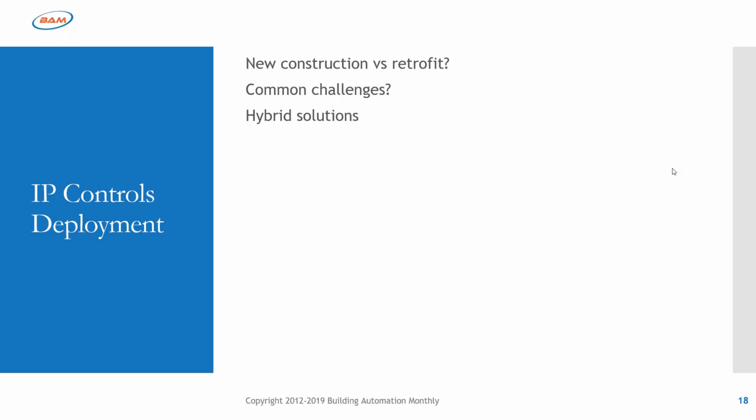The biggest issue that BACnet solves, that IP, HTTP, all of that, can't solve is strong data typing and strong service definitions. Here's the deal. Let's say we got rid of BACnet today and we all switched to MQTT, or we all switched to HTTP. The problem is you have to get consistency across every manufacturer adopting the same services, and that means they have to have the same or a similar code base to execute the same functions, like the read property, write property, or create device service.